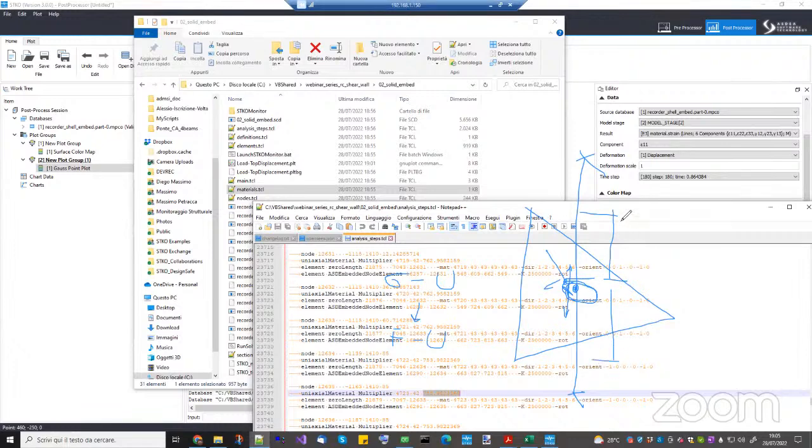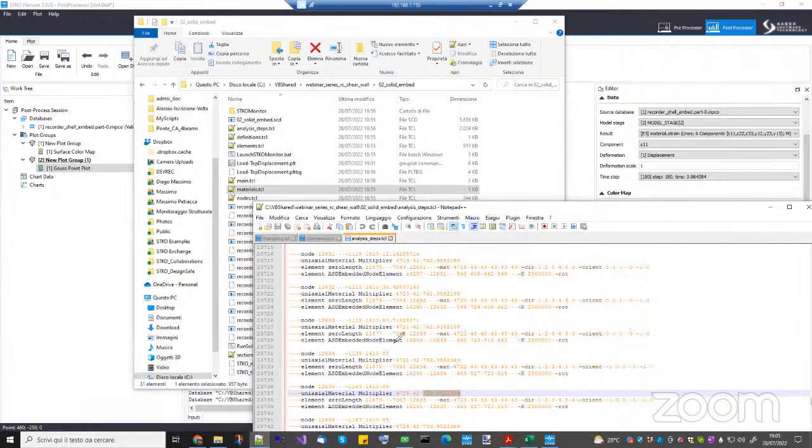So with the circumference and the tributary length, I obtain the tributary area. So I take your stress and multiply it by the tributary area, and I convert this one into a lumped force displacement item, okay? So that's why here you see a duplicate node. This duplicate node will be embedded, okay?